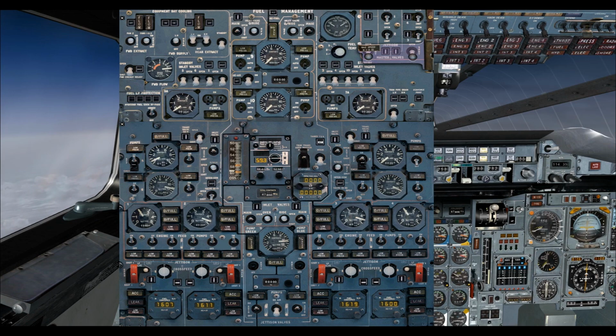The next thing we have to worry about is that we notice our center of gravity is at 59.3. So we're going to have to move fuel forward now. So we're going to move fuel forward from tank 11 into tanks 5 and 7. So we're going to have to turn the pumps back on in tank 7 so that fuel can be pumped out. And then once our CG reaches 59%, we will close up the trim transfer and leave things as they are. And we'll probably be good now for the remainder of the flight in terms of center of gravity.